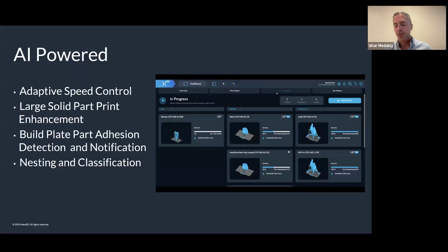There is an exposure to the slice. The build plate, excuse me, needs to go up. There is a specific speed that it's pulling away. There is a wait time. Then we're going down, we're squeezing the resin. All of those steps have a physical model that is attached to it.